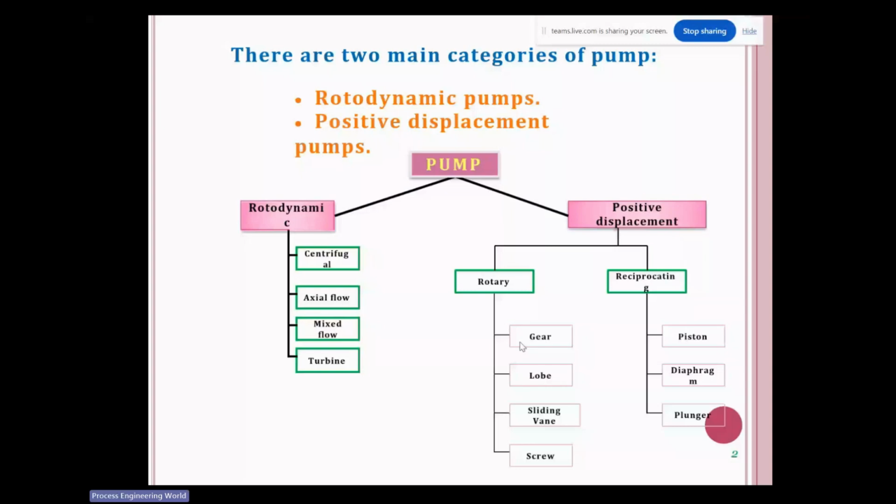So what actually is the difference between solution and slurry? Both contain solids, but as one of my friends says here, a solution is a homogeneous mass, and a slurry is a heterogeneous mass where a certain percentage of solids is not dissolved. It is in a suspended form, or it might not be suspended but precipitated in the vessel. So this is the basic difference between solution and slurry.